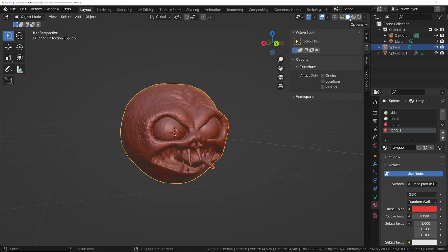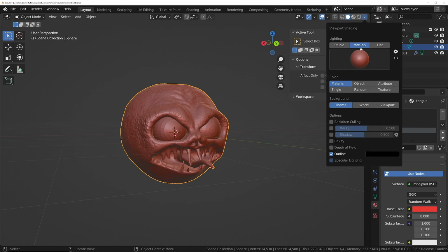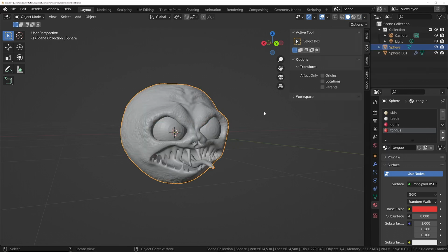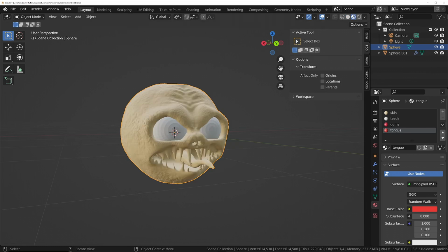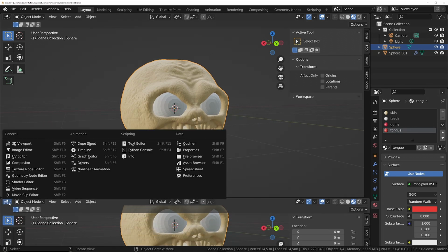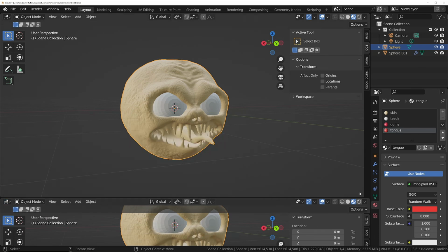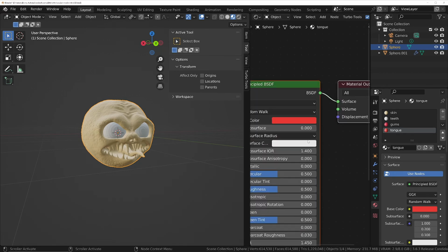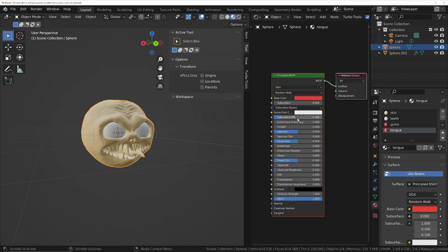Let's make sure we come out of matcap mode now. So we go into studio mode, and we'll set this to be material. And in actual fact, we probably want to go into one of the rendered modes. We'll go into the preview material mode, that'll be easier. And we'll bring up the bottom and turn it into a shader editor. In fact, let's do it on the right instead. And now we're left with the principled BSDF.